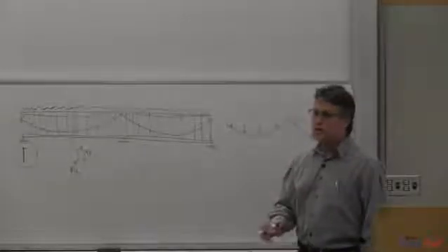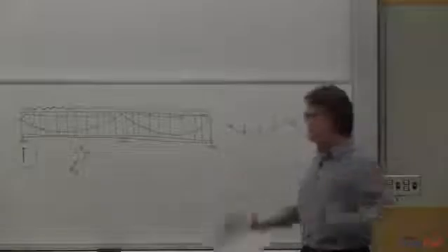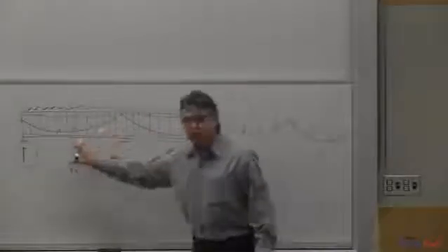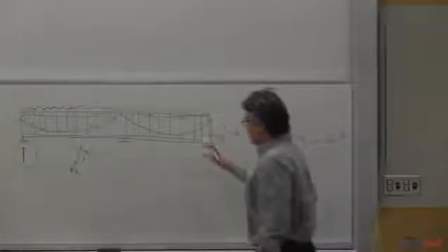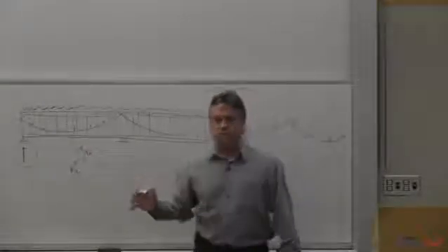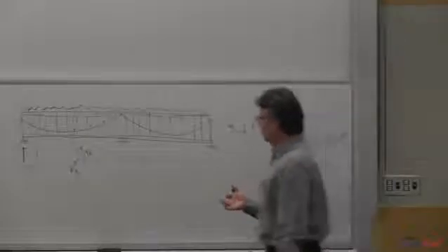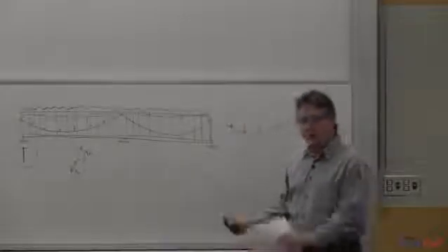They created real reactions because when the beam was stressed, it tried to lift up, and it couldn't. It was held down by the middle support. So it generated real reactions. So those created moments that needed to be accounted for along with the applied load moments. So the equivalent load moments, concrete only, useful only for stresses. Then we came back and we did use those again. Those were very useful in finding the secondary effects. So yeah, they were useful for one other thing other than calculating stresses, for actually determining what the secondary moments and reactions were. But we're back to the full system, the full statically correct system, not a concrete only type of system.